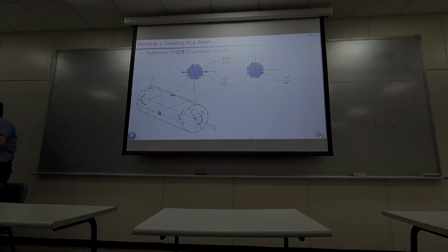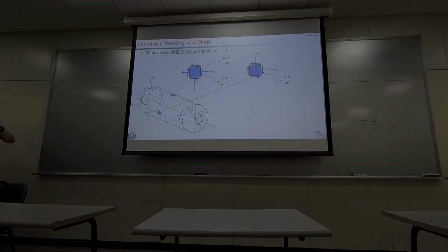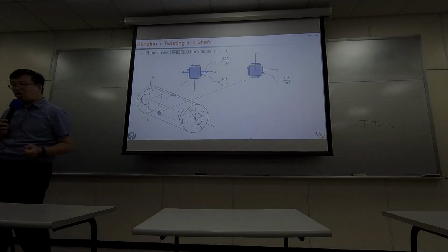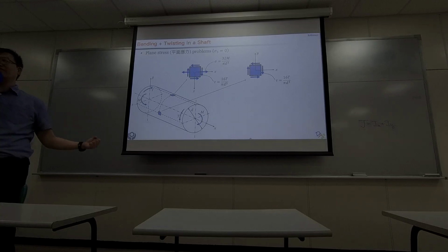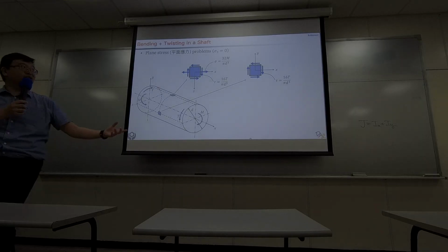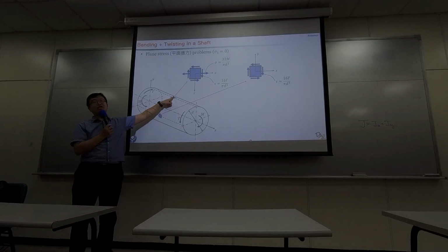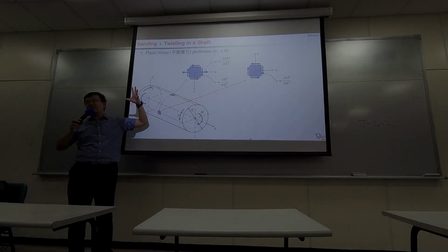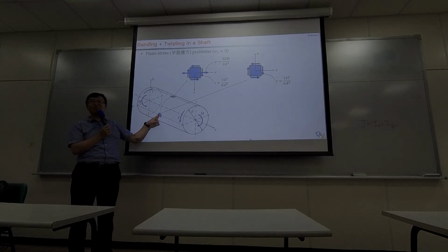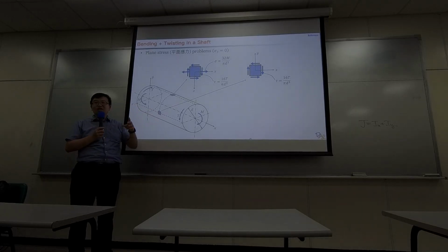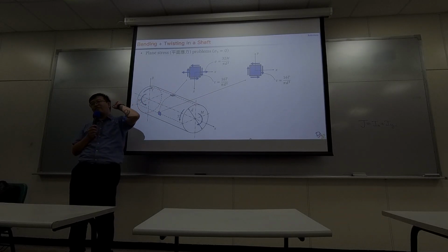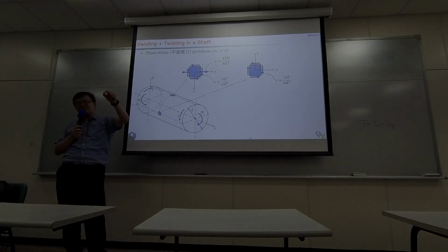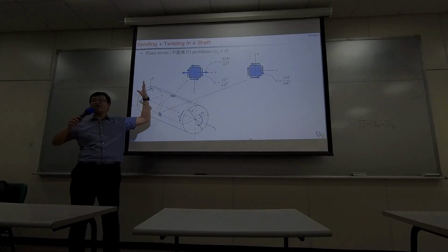Okay. So if some part of the geometry is carrying the most load, it will probably fail first. Do we care about other points? Actually, we don't, because this one fails first. If this point fails, the whole design fails. So we will never care about the other points that will not fail first. So in mechanical design, we need to find out the worst-case position, where the point fails first. If that point is safe, then we are safe. Okay?